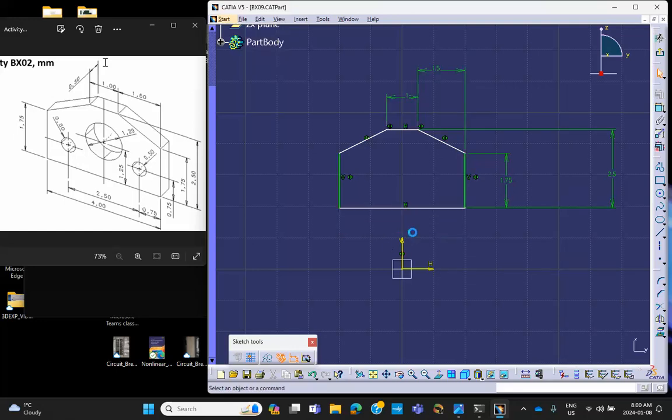Let's see now. Okay, I can't dimension this. The reason is clear, I hope. You understand why? Because when you say this is 1.5, and this is 0.5, that makes this thing 2, which automatically makes this thing 4. If I try to dimension this thing, it's going to say you can't do it, because you have already told me, because of the symmetry condition, it already knows that this is 4. Okay, I think that'll do it. I don't think I forgot anything.